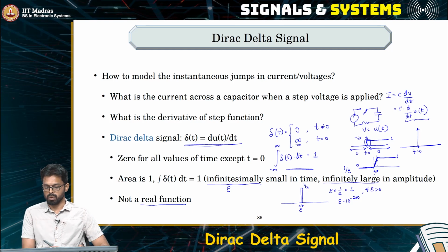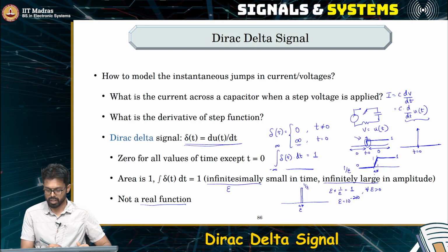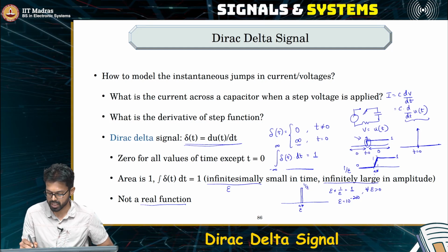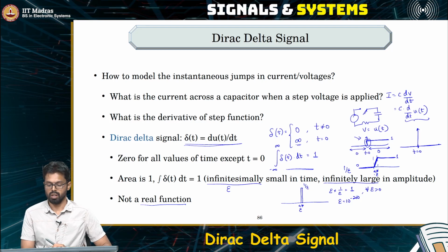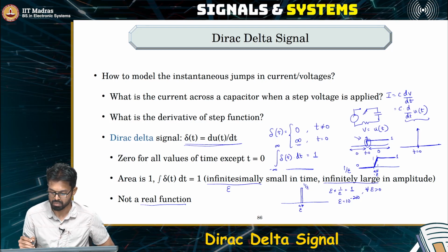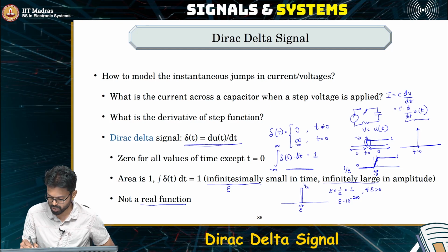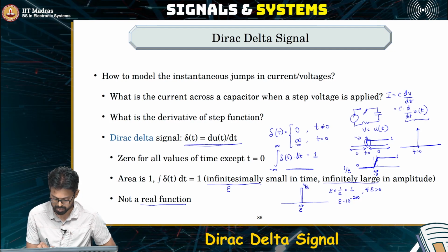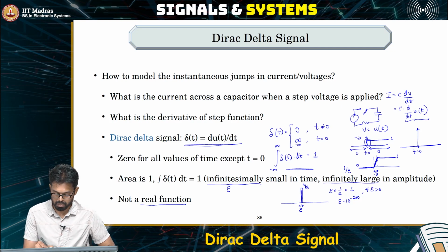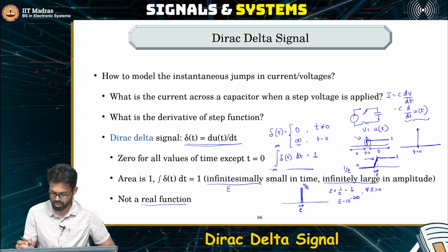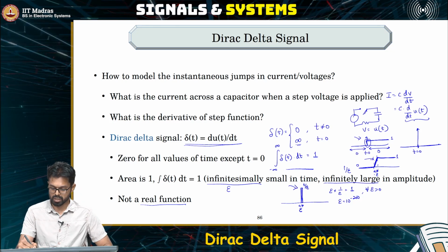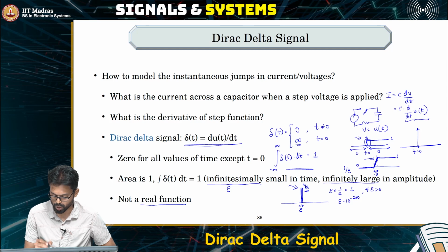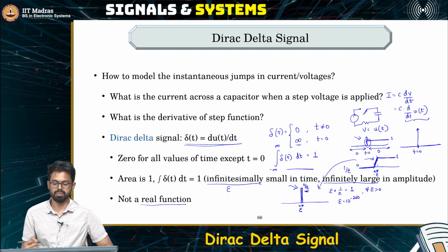Of course, we know that all the electrons travel almost with the speed of light, or the electric field travels with the speed of light. So almost with the speed of light, it goes from 0 to 1, which means the time taken here, epsilon, is really, really small. So in this duration, when you compute the slope, it's almost like 1 by epsilon, and the duration for which the slope is non-zero is epsilon, right? So the derivative in this region turns out exactly to be this rectangular function, because here it's like a straight line. A straight line's slope is just a constant, and that constant is 1 by epsilon.